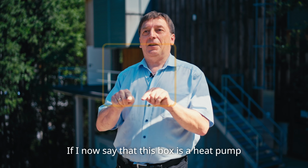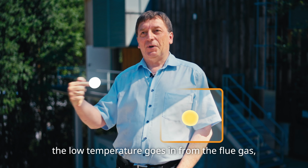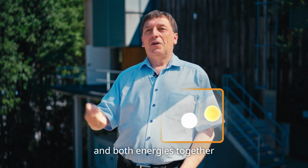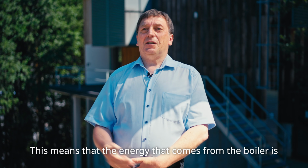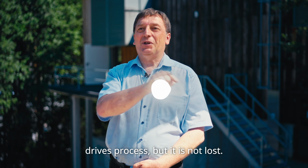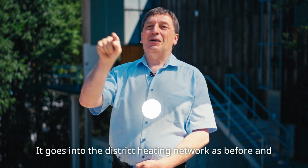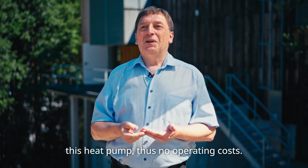If I now say that this box is a heat pump and the driving energy goes in, the low temperature goes in from the flue gas, and both energies together go into the district heating network. This means that the energy that comes from the boiler is fed through the heat pump and drives the process, but it is not lost. It goes into the district heating network as before, and therefore I have no costs for driving this heat pump, thus no operating costs.